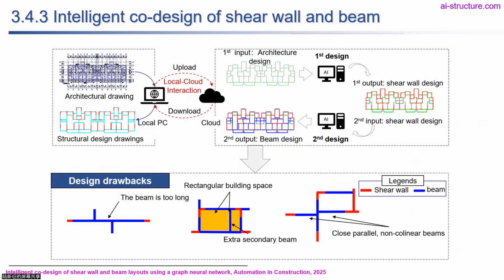And also we can combine the shear wall design and the beam design together. It is interesting that when I was training the students, I trained them one by one. The number one PhD student worked on shear walls and the number two student worked on the layout of the beams. After that, I read a lot of papers that separate the layout of shear walls and beams, but it is not reasonable. When engineers do the design, they lay out the shear walls and the beams together. So we proposed an algorithm to do the layout of shear walls and beams at the same time, because otherwise they cannot fit very well with each other.